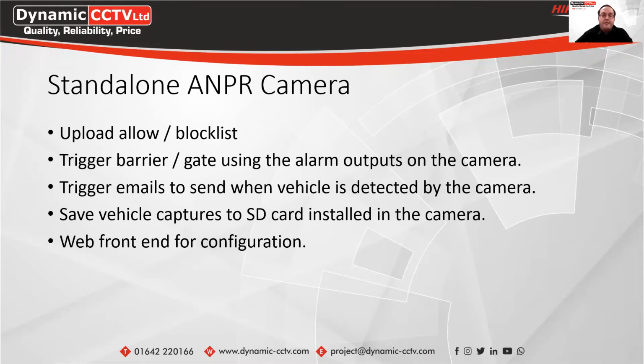In order to save the vehicles, you can insert an SD card into the camera itself, and this will save captures of when the vehicle's been detected. It will only save a picture of the actual vehicle. It won't save a video clip. If you need to be able to have a short video clip of the vehicle being detected, then you'd need to use the ANPR camera in conjunction with an NVR or DVR in order to be able to have that short video clip recorded when the vehicle is